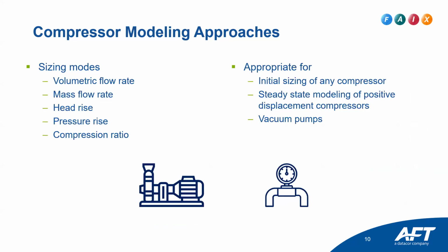So the other way you can configure your compressors is in sizing mode, and this is the most broadly applicable approach. It doesn't require you to have a pressure curve, and it can get you in the ballpark by identifying compressor performance requirements before selecting a compressor, even if you are going to be dealing with a centrifugal compressor. But basically, the outlet and inlet pressures are determined by the interaction with the broader system. And this also works for any positive displacement pumps or even the more exotic designs that I mentioned earlier.